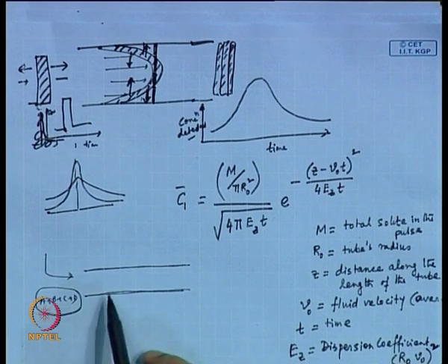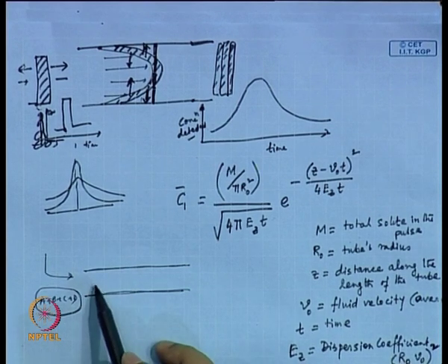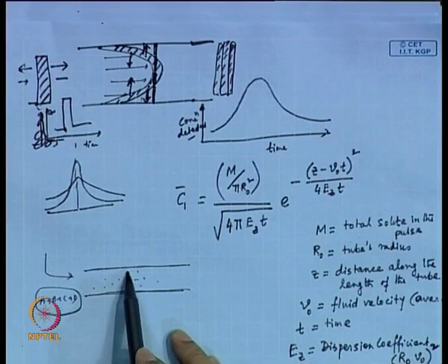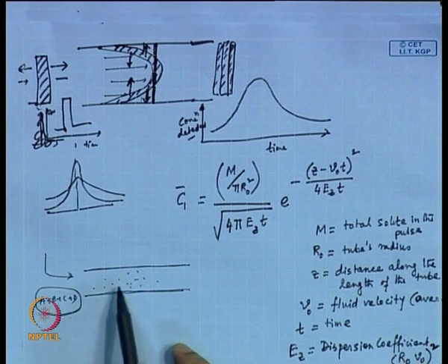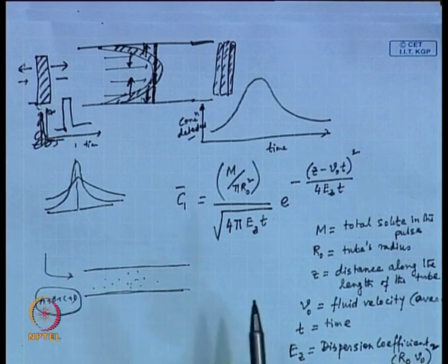And then you have this adsorbent. In a conventional chromatographic unit, you have a packed bed, meaning a bed filled with beads. So flow can take place through the sides of these beads. That's the idea of a packed bed. Now this wall is coated, it has a special coating, and this wall will adsorb. So when A plus B plus C plus D are flowing, they have some preferential adsorption. Maybe A is adsorbed more, B is adsorbed less.